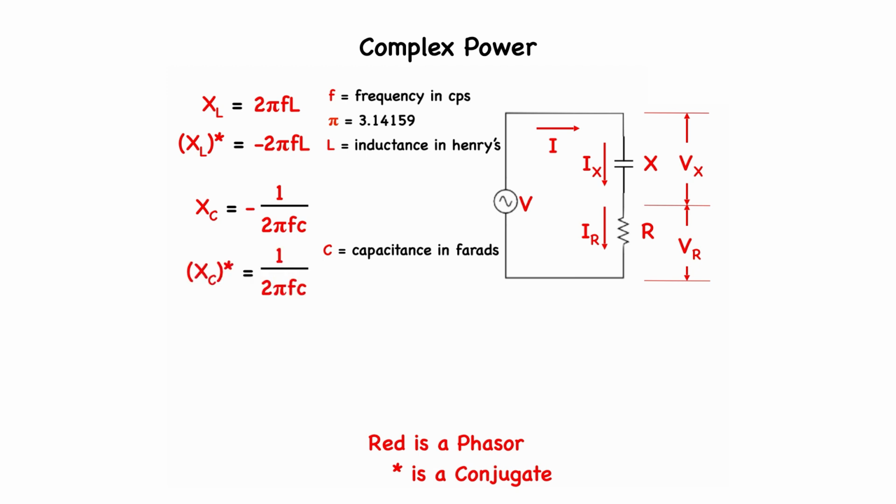In other words, we would drop the minus sign, because when we pick up these reactances in our circuit, we apply the J operator. But once we apply the J operator by taking the complex conjugate of them, we reverse the sign of that J operator, essentially.